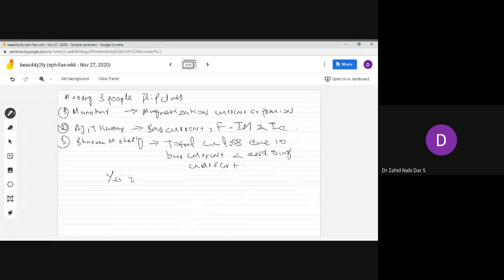This is nothing but the stator slot pitch, which is pi d, that is the total circumference, divided by what? Pi d by SS. What is SS? SS are stator slots. See here you saw ZS. ZS is total number of conductors.